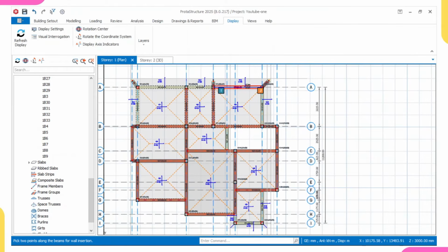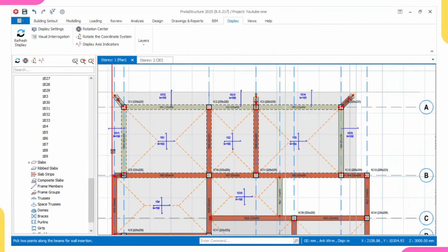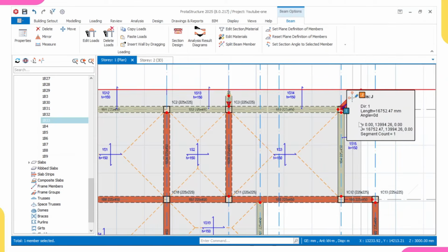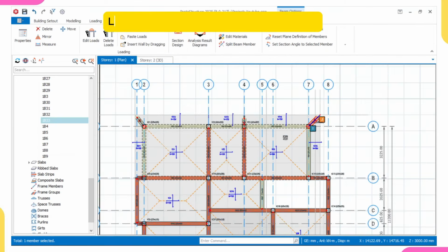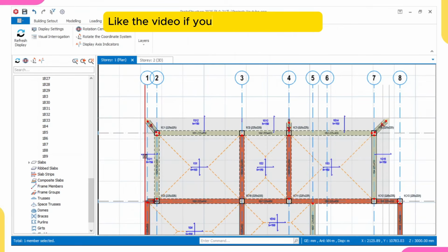So I've applied wall load to this, but don't forget, here we'll be having block wall. Oh, sorry, let me delete this wall load. Delete wall. And there's no wall load there. Okay. So remember, here now at this edge, there is block wall along this edge. But we cannot apply wall load here. What to now apply here is line load.